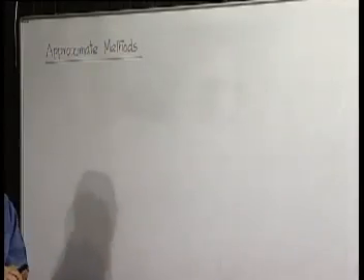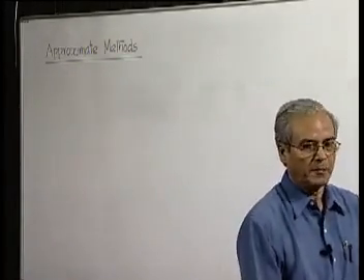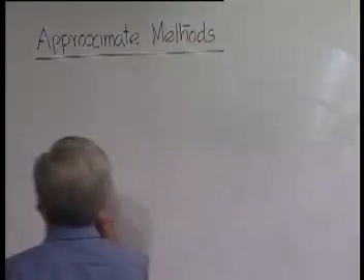The approximate method, what we have discussed in the case of lump parameter system, can be extended to continuous bodies also, because continuous bodies can be considered to be lump parameter systems with infinite degrees of freedom. So one of the most prominent methods which we have discussed, we will apply here by slightly modifying that method suitable for continuous body, and there we come to our Rayleigh approach.